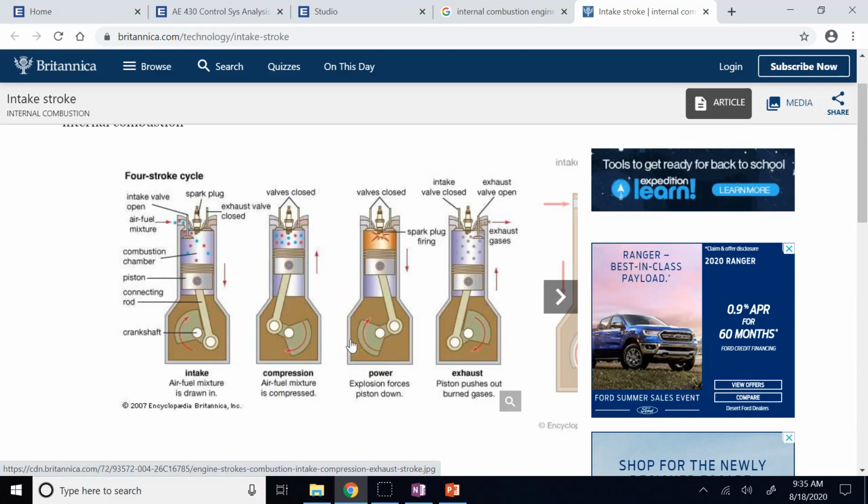So what happens? Yes, the crankshaft will rotate faster, and the faster it rotates, again, the bigger the vacuum is going to be, the more fuel comes in, and you see that's this vicious cycle, right? The system is just boosting itself more and more and more until what?